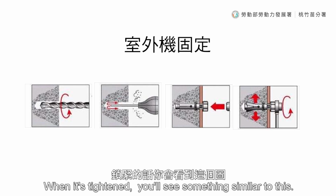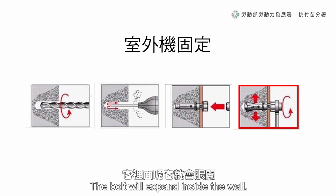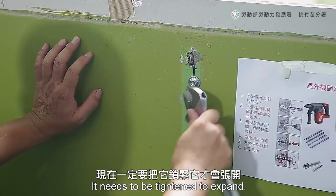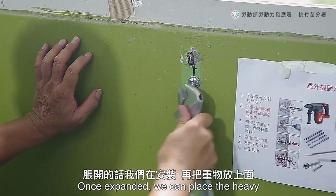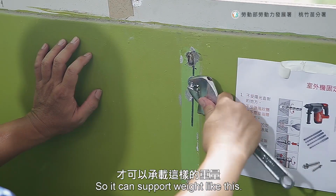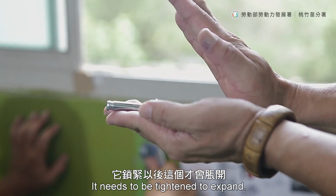When it's tightened, you will see something similar to this. The bolt will expand inside the wall. That's why it's called expansion bolt. It needs to be tightened to expand. Once expanded, we can place the heavy outdoor unit on it so it can support weight like this.